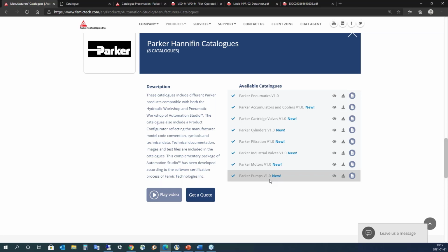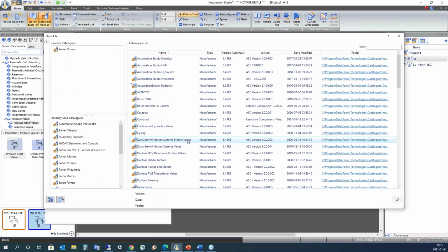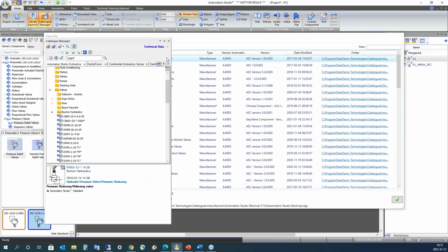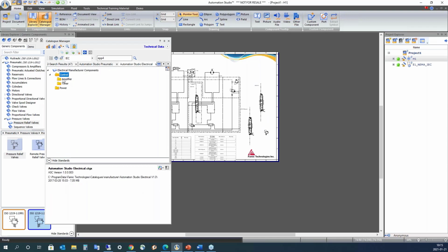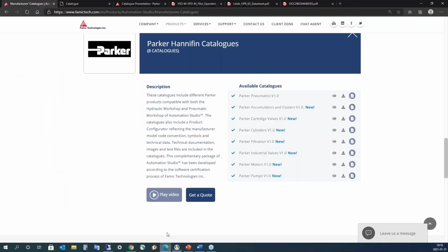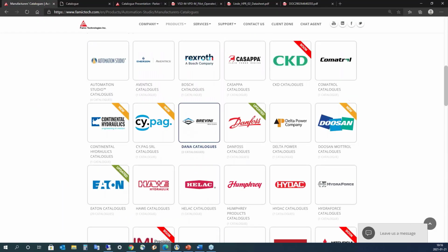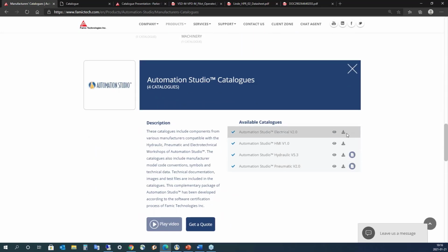So two things here. Those controllers are available in Automation Studio, or we make them available in Automation Studio, and then you have two choices. You could build the logic directly in Automation Studio with the tools that we offer. We have a block diagram module, we have an SFC, and a lot of already well-known ladder logic, with new ones upcoming in 7.0 that you could use directly in Automation Studio. Or you could link those controllers using CAN or OPC connectivity.